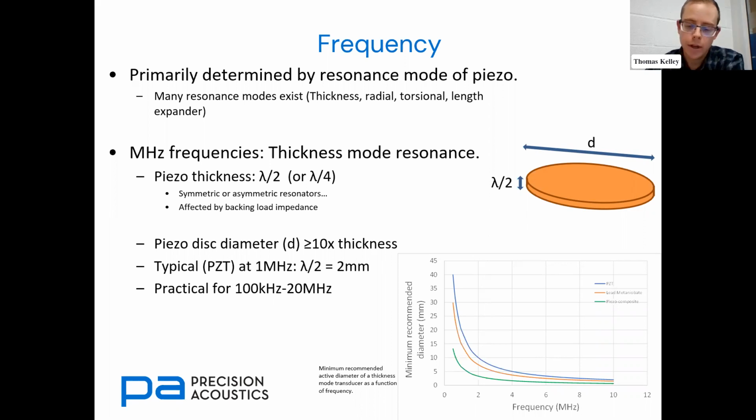Yes, I guess so. You could consider the capacitance of a transducer element to be that of a parallel plate capacitor, so epsilon naught A over D, with A being the area and D the thickness. Piezoceramic elements obviously have an inherent capacitance, but the capacitance in PVDF film is very much greater, owing to the thinness of the PVDF film.